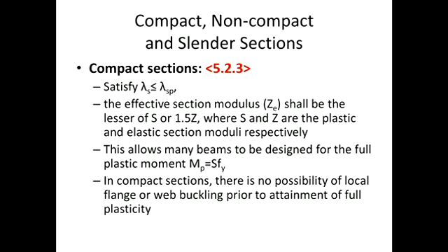And then the standard gives us the definition of how we can determine the effective section modulus. For most of the compact sections, you will find that the value of My will also be equal to the value of MP. So MP is equal to S multiplied by Fy.